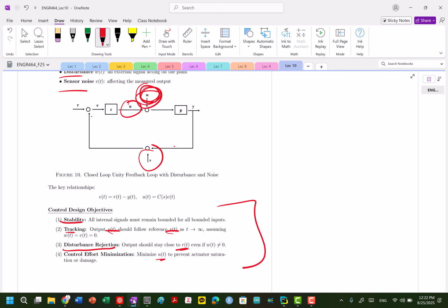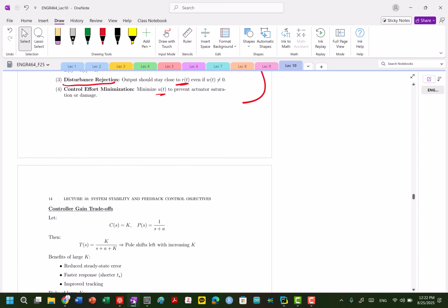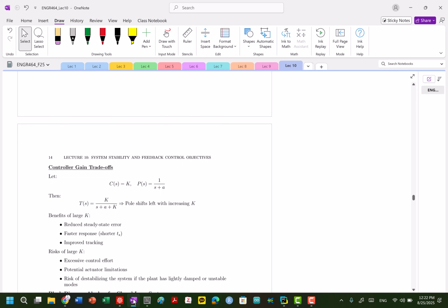When we increased, for example, that K gain, you can think of it as the signal that's sent, that control command. It could be horsepower. It could be torque. It could be lots of different kinds of inputs. And you could be plugging in a value that's not even feasible or so expensive where it's not possible to control that system. So we have to think about that and the trade-offs and make sure that what we're developing is actually a realistic system.